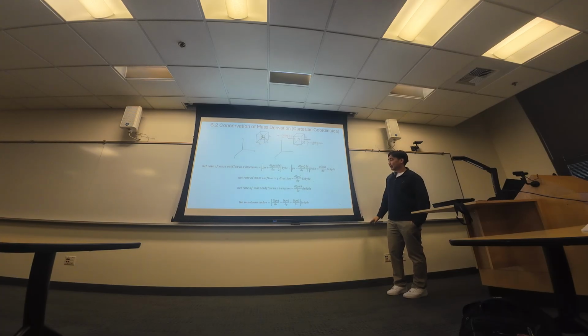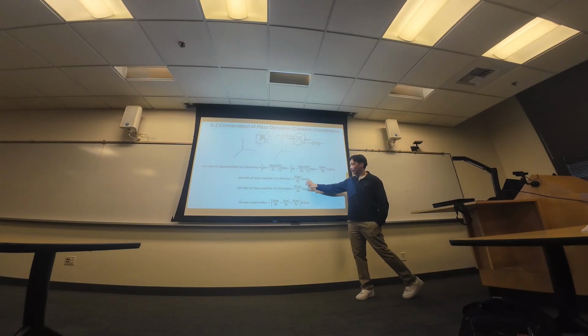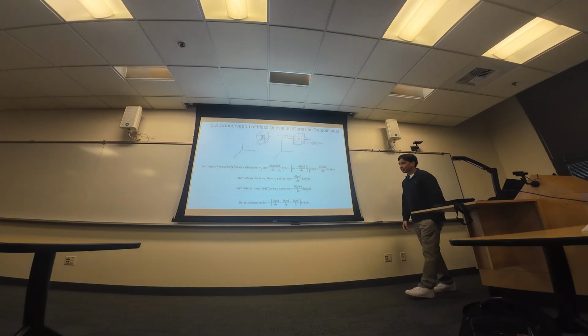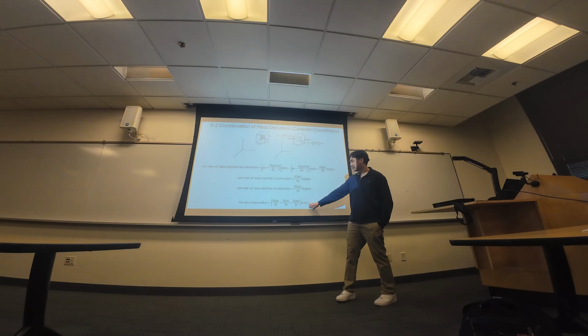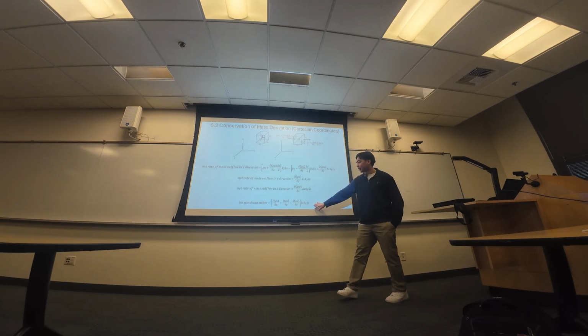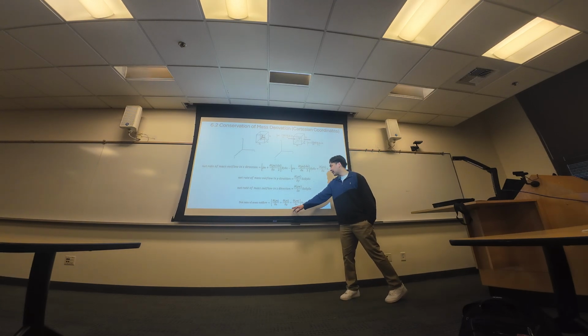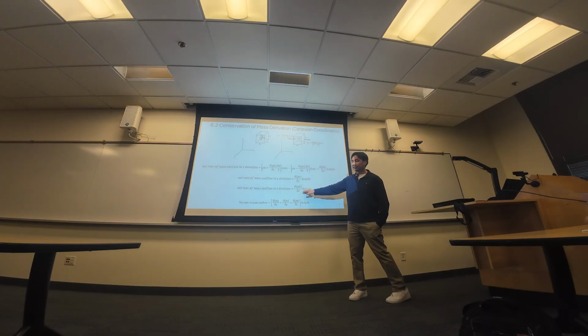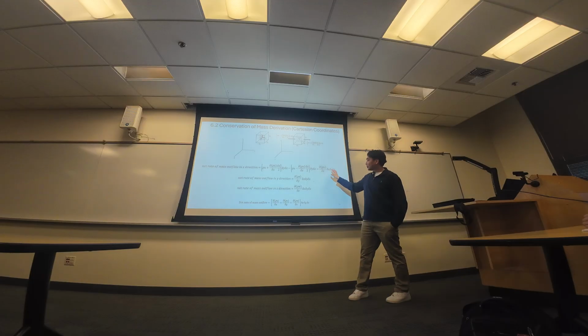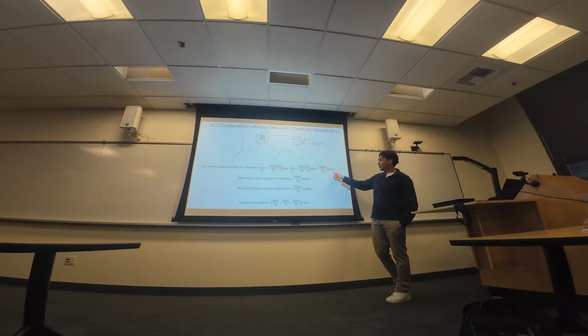Okay, and then you can do this equation, we did it for the x, respectively in the y and z direction. Okay, and then your net rate of mass flow, totally, you can just combine them and this is your total output here, respective to x, y, and z. It's essentially adding all three of these terms, except you're factoring out your delta x, delta y, delta z.